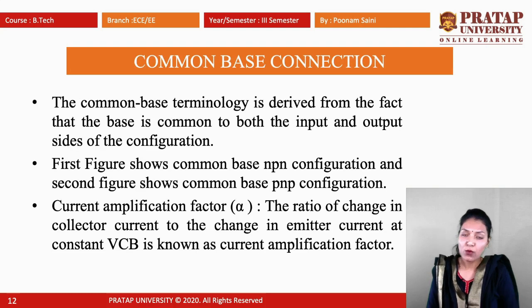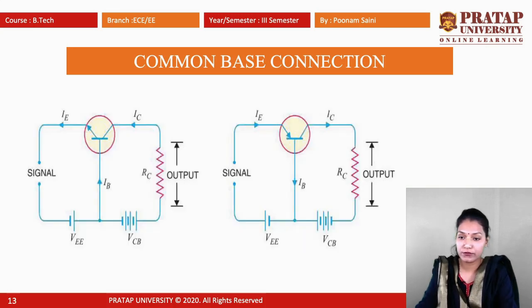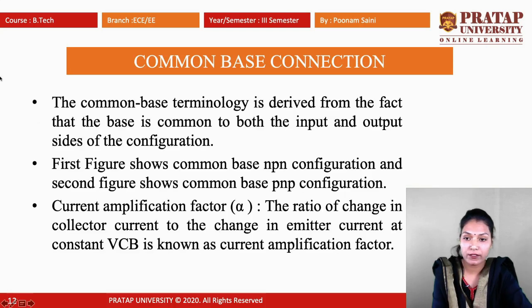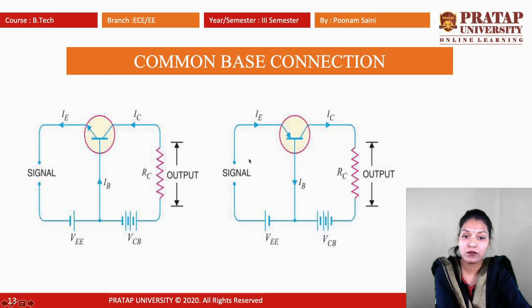So what is common base? The common base terminology is derived from the fact that the base is common in both the input as well as the output side of the configuration. In the first figure is the common base NPN configuration, and the second figure shows the common base PNP. This base is common in input, this base is common in output.